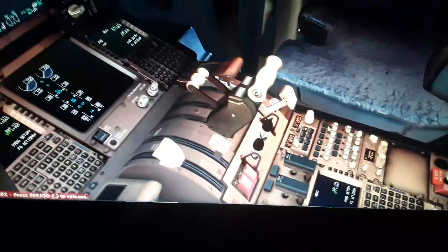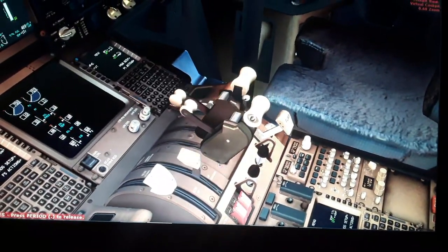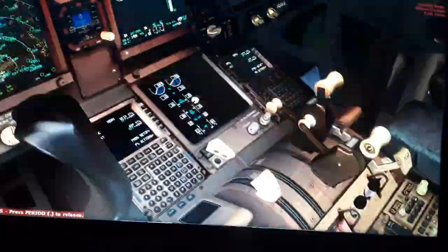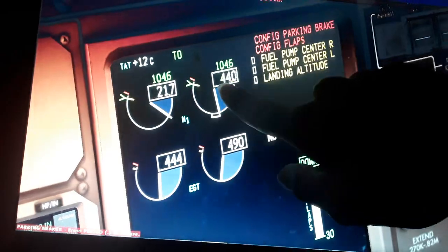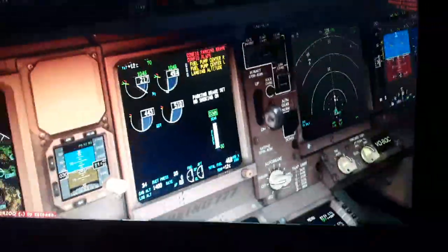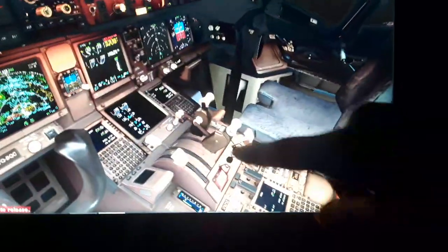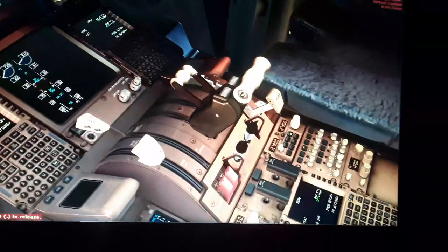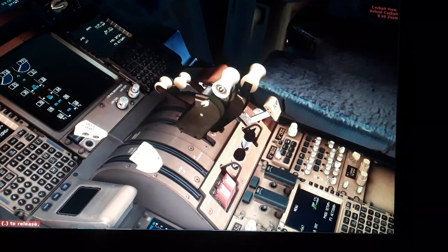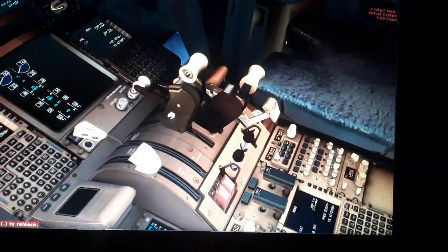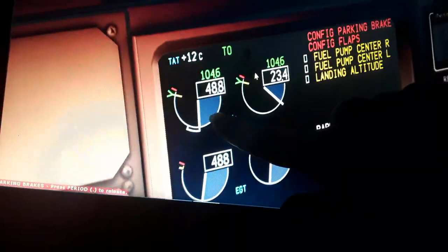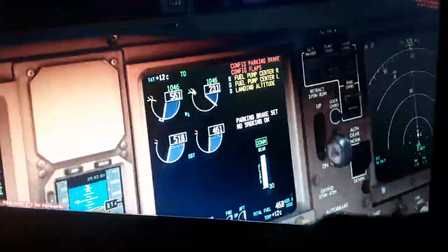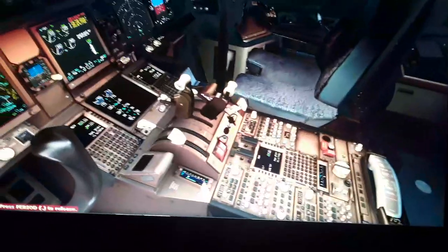So we can move one engine at a time. Also, we have a failure, you can see. Also this retract. So you can see the N1 here, you can see 44-46% for the right engine, while the other one is at idle. Move both together. This is how well this is simulated. The variable thrust. If we have an engine failure, we use only one engine. So you can see N1 at the left engine now, idle the other one, the right engine.